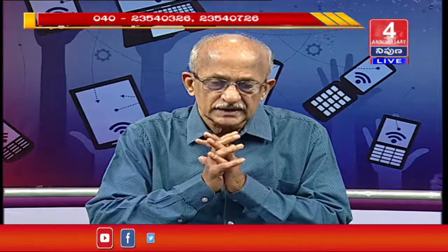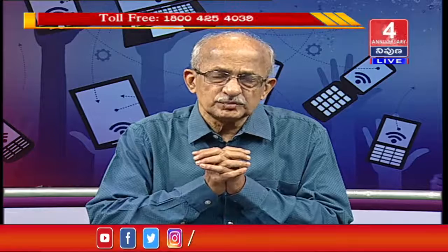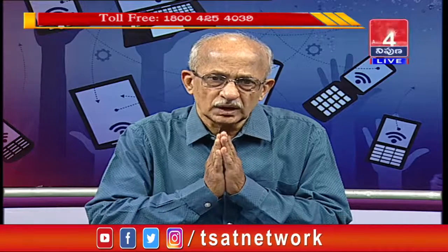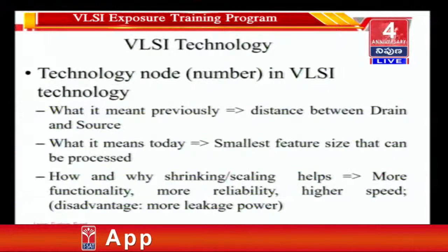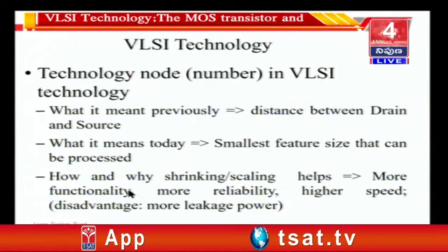In addition, once the transistors scale down to a smaller size, the drain and the source come closer and closer to each other, and this increases the leakage power. We'll see what is meant by leakage power in the next few slides when we talk about the transistor characteristics.